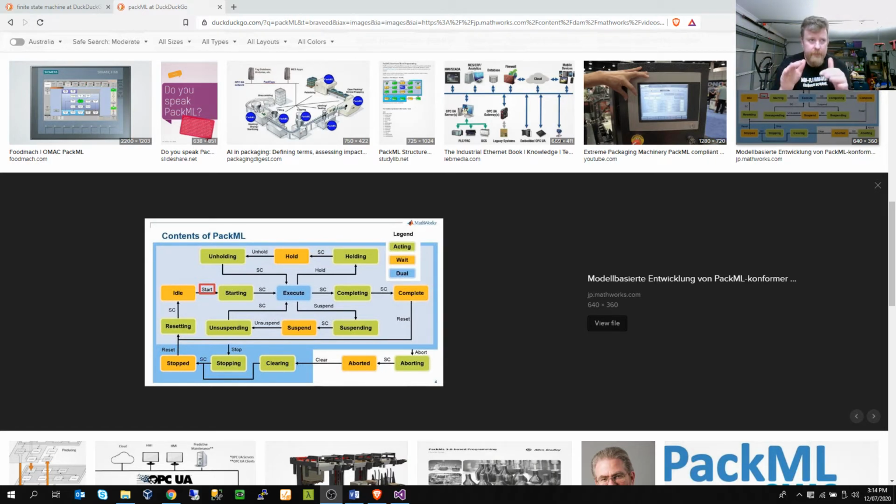So straight out of the gate, one of the first things people always ask is, what PLC am I going to use? The answer is one that's supported, cost-effective, time-effective, and reasonable to use for the particular project. So you're not going to want a $10,000 Allen Bradley processor for some mixing plant. You're also not going to use a $100 processor that doesn't have Ethernet on it, because they're just a pain to program.